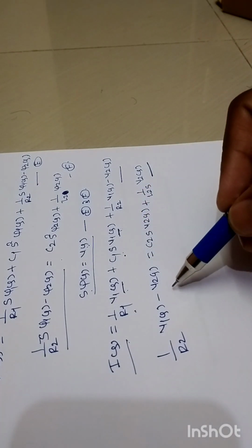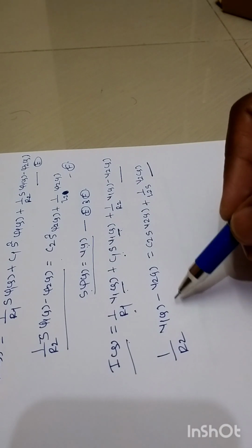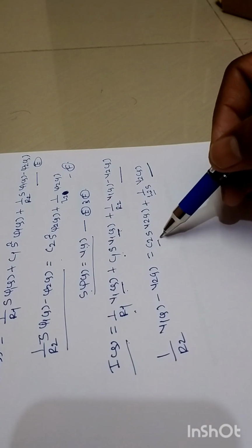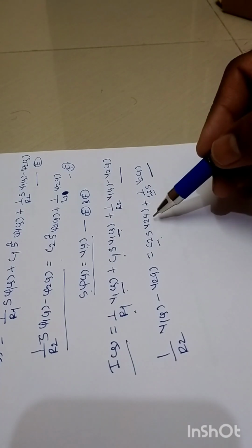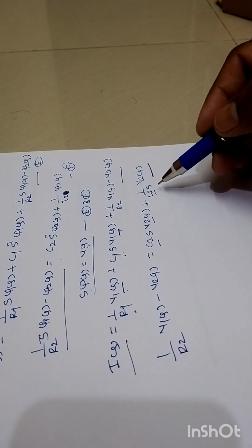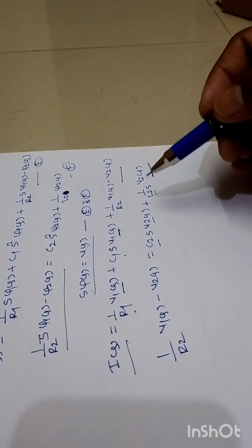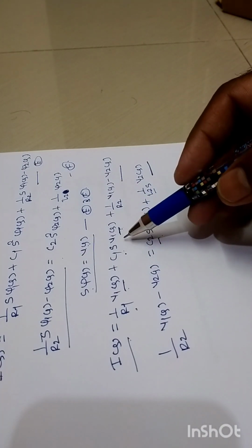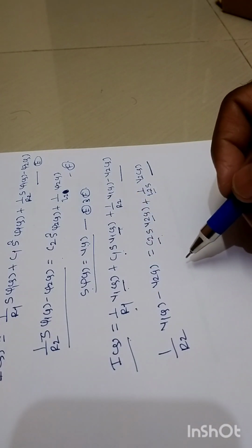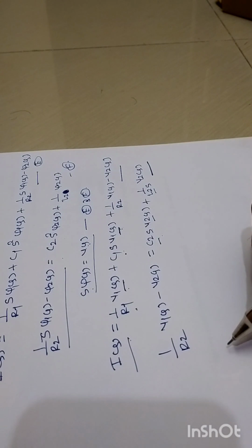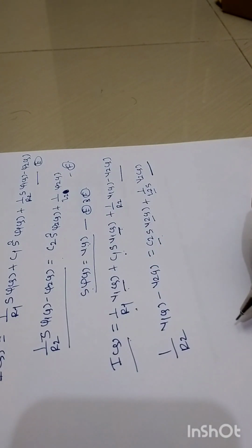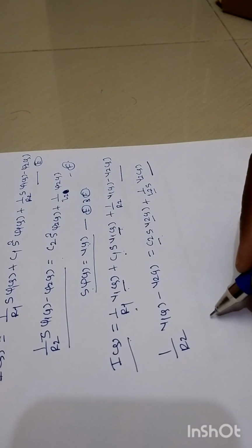Similarly, when we carefully try to see the next equation, the coefficients of C2 and 1 over L2 are the same. The coefficient for C2 and 1 over L2 is nothing but what? V2 of S, means the same potential difference across C2 as well as across 1 over L2. Now if the voltage is the same, means these two elements are connected in shunt form. As a result of this, definitely we can convert these two equations into their equivalent electrical circuit.